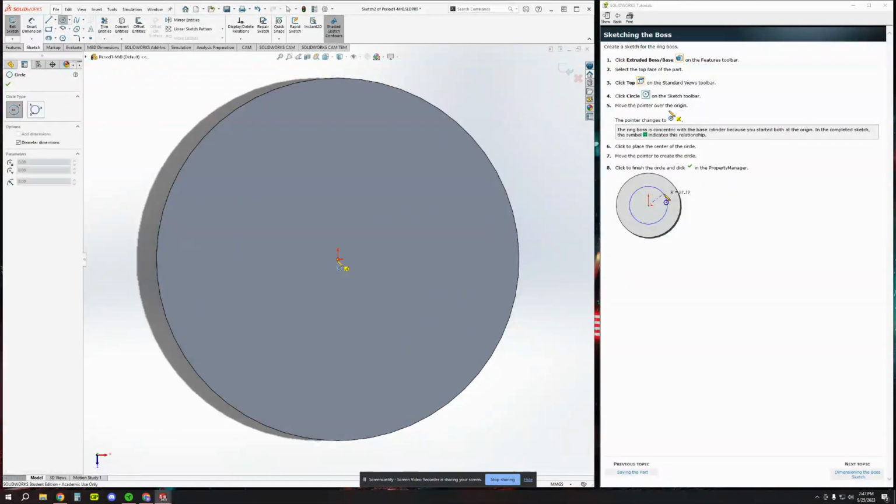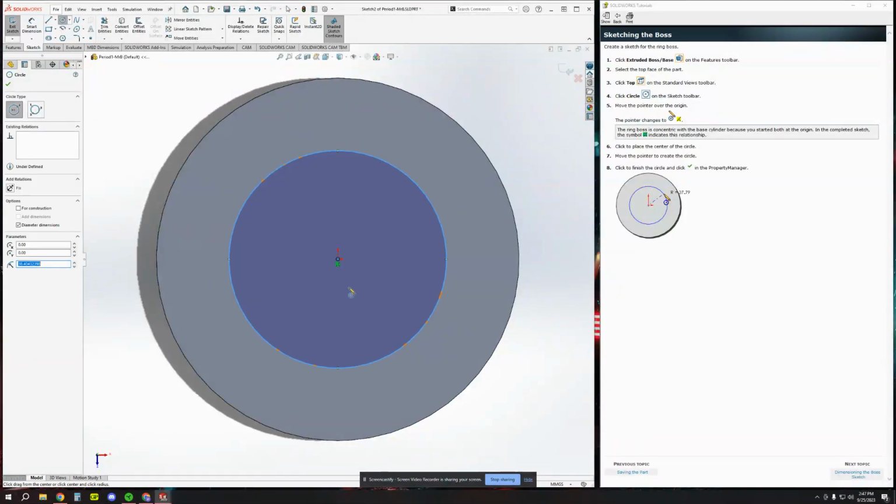So we hover over the center. You'll see the yellow icon that shows that there's going to be a constraint. It will constrain it. It'll hold it right to that center point. And just pull it out. It doesn't matter the distance. Just pull out, go like that. Okay. So you will click the center, drag it away and click again, and that will draw this circle. So we got the what is it and the where is it.